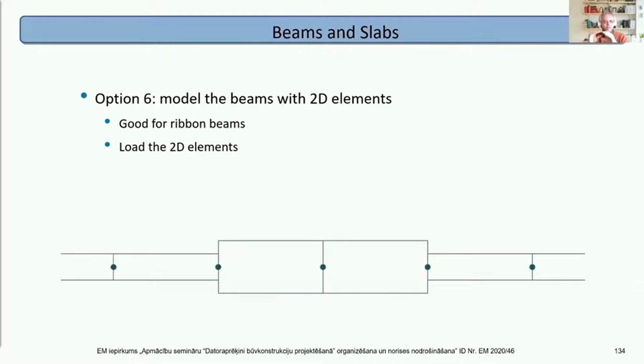Now, the reality is there will be a flush top surface, a step in the bottom surface, and there will be a small amount of T-shaped behavior at the junction, but in engineering judgment, not much. There might be in your case, but in this case, not much, therefore we can ignore it. And again, we just make the rectangular sections work and say, well, there's a little bit of flexibility, whatever, between the two. All models are wrong. Some models are useful, and we make the structure work the way we want it to work.